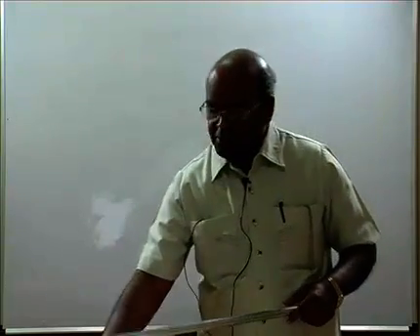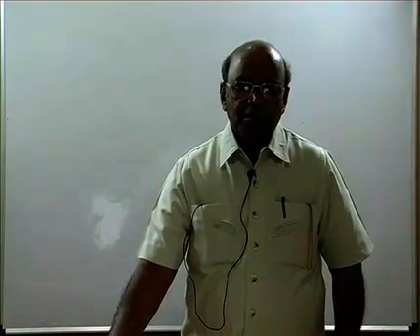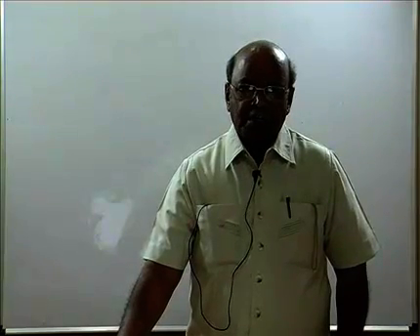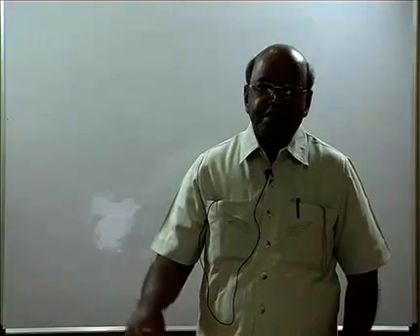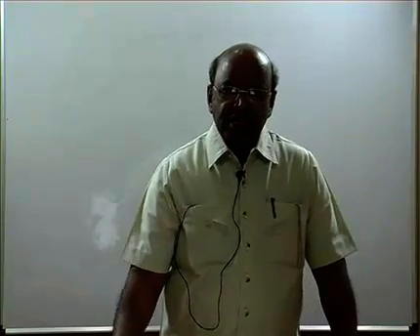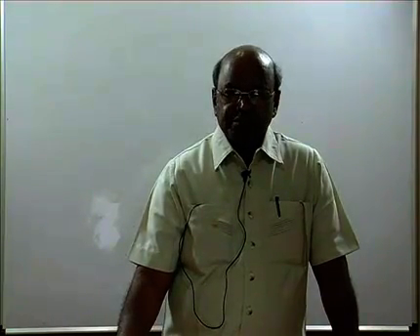Now you can see in this figure, it is done on a common XY line. Previously we have seen them done separately on different XY lines. All the three cases you can do at one place on a common XY line by naming them differently. So same thing: A dash B1 dash, A B1 represent parallel to both.